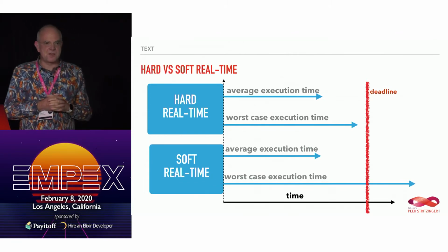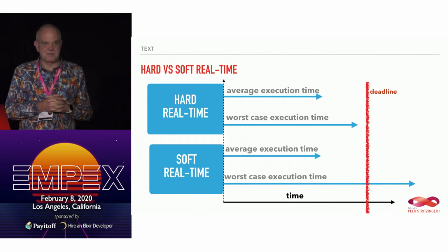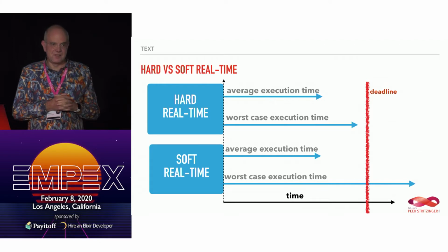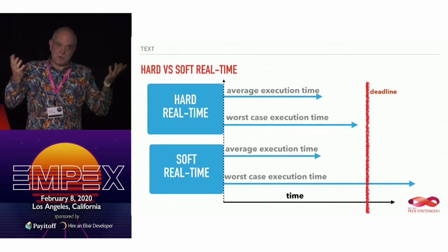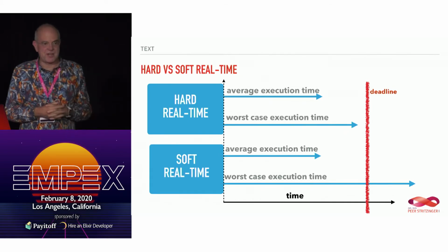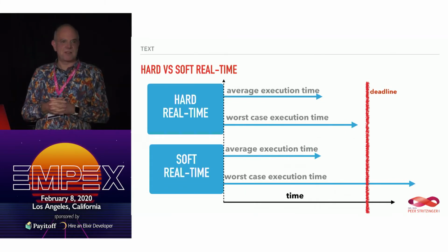But to be honest, hard real-time is also soft real-time, because it's all probabilities. If your CPU breaks, you will miss your deadline. If you have 4 CPUs that work in lockstep and all kinds of things, well, if one breaks, it's fine. If 2 break, it's also fine. But if they all break, or the power supply breaks, you miss your deadline. So there are always probabilities, because the real world doesn't have 100%.